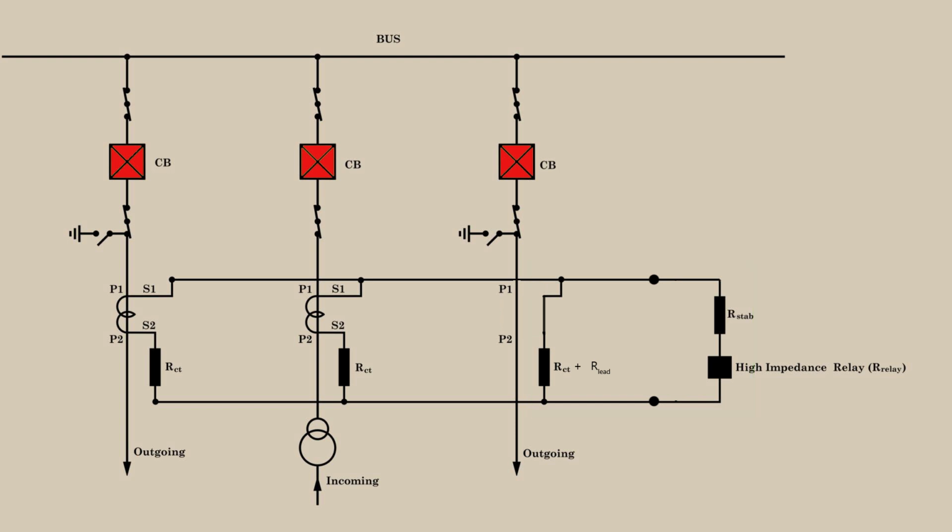If we neglect those, then due to the secondary current, which is theoretically the reproduction of the primary fault current of the CT, as we assumed, a through fault at that CT, the CT becomes saturated. So theoretically, the secondary current will be the reproduction of the fault current through the CT primary.